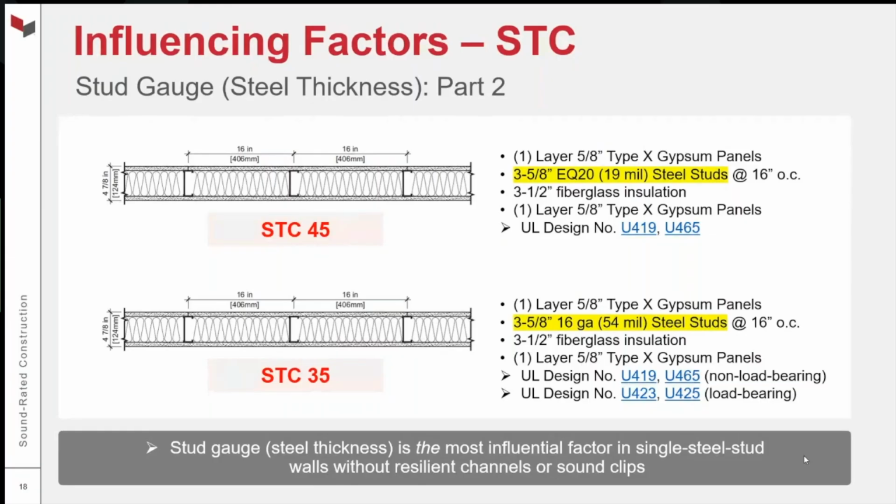Again, the example I gave with limiting heights, where the design STC is based on 25 gauge studs, but in practice, in reality, you have to build with 16 gauge studs, and there's a huge difference in STC. Doesn't matter what wallboard you use, doesn't matter if you change out your insulation, you're not going to be able to overcome the stiffness of that framing.